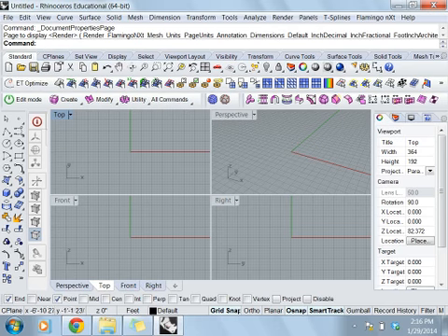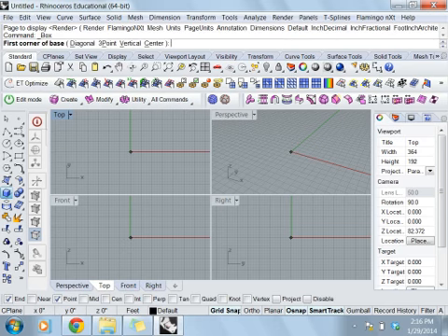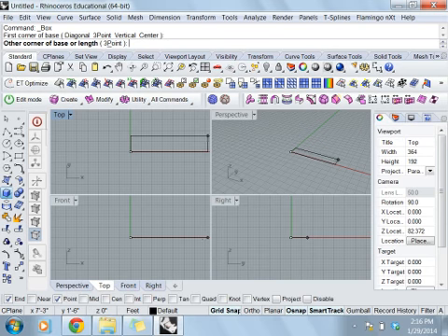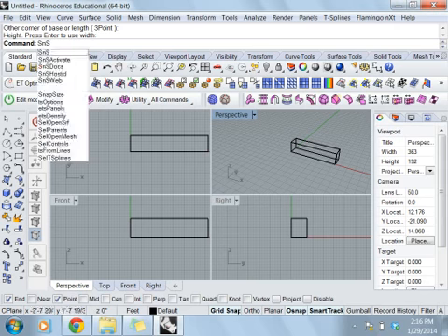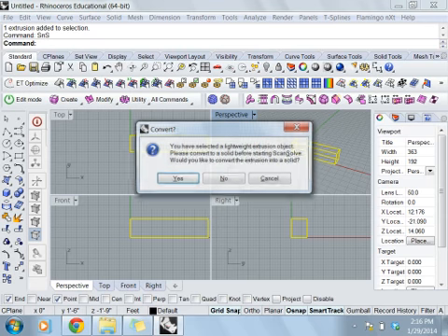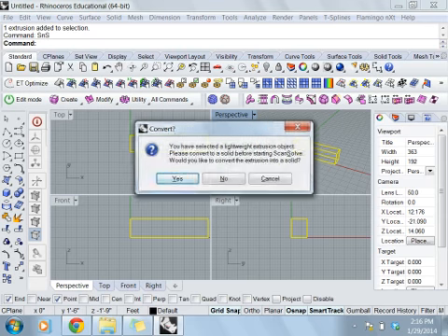Okay, so I'm going to start with just a simple solid beam here. And so before you use Scan and Solve, it uses a closed polysurface. To find out if your object is closed or not, if you type in SNS to open Scan and Solve, choose your object, it'll come up with an error, and you need to convert.